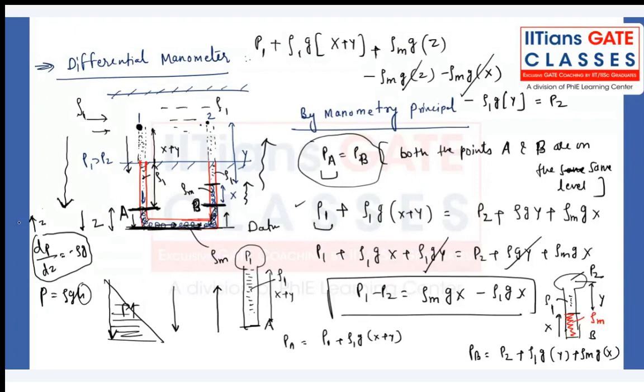How it is coming from the Navier-Stokes equation, we have equated the fluid at rest condition, so the acceleration part will be zero. There is no viscosity as the fluid is not moving, so viscous forces will be zero. Ultimately I will be left with only these two terms, pressure forces and the body forces in z direction. Now we will solve the questions, and from the question things will be more clarified, I hope so. Let's see.